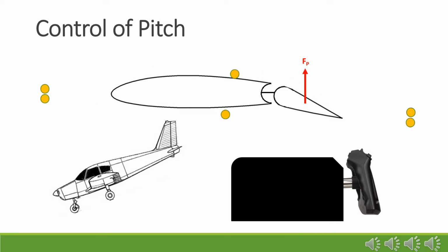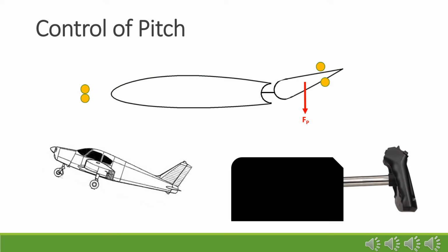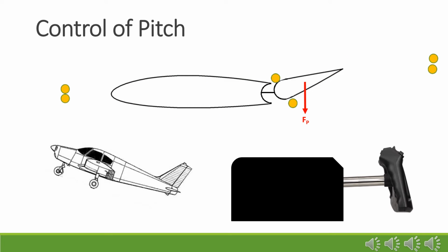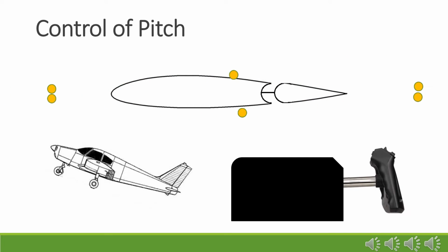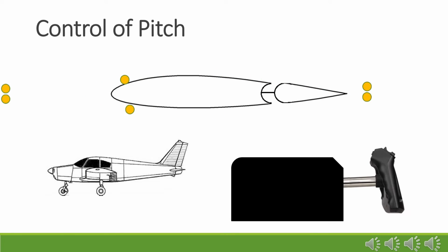By pulling the control yoke backwards, the elevators are rotated in an upward direction. The normal, drag, and perpendicular forces are applied, with the perpendicular force pushing the tail downward. This downward push on the tail of the aircraft causes the nose of the aircraft to rotate upward, and the aircraft climbs. By returning the control yoke to the neutral position, the elevators once again return to the center position. The normal and perpendicular forces are eliminated, while the drag force is minimized. The aircraft would stop changing direction and continue on its current pathway, which could be a climb, descent, or level flight.